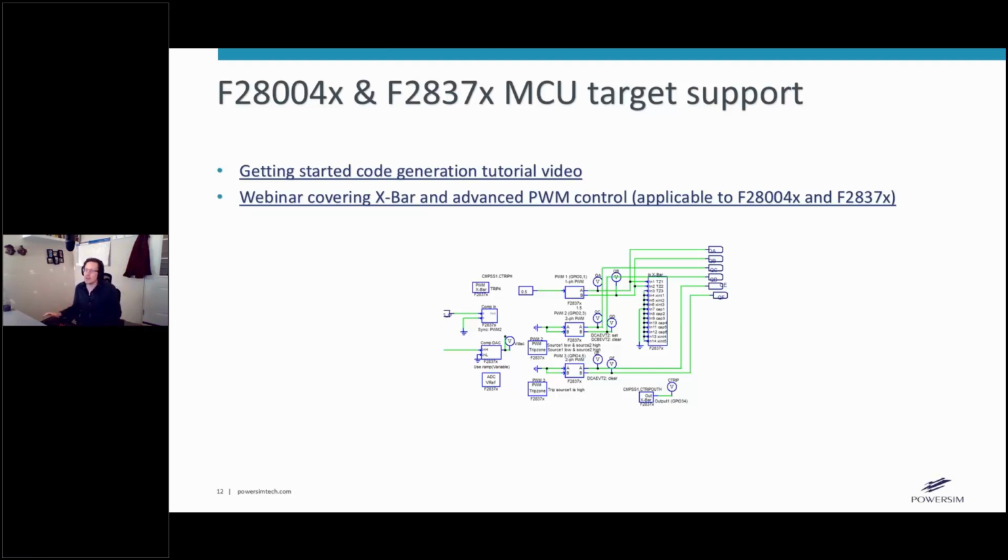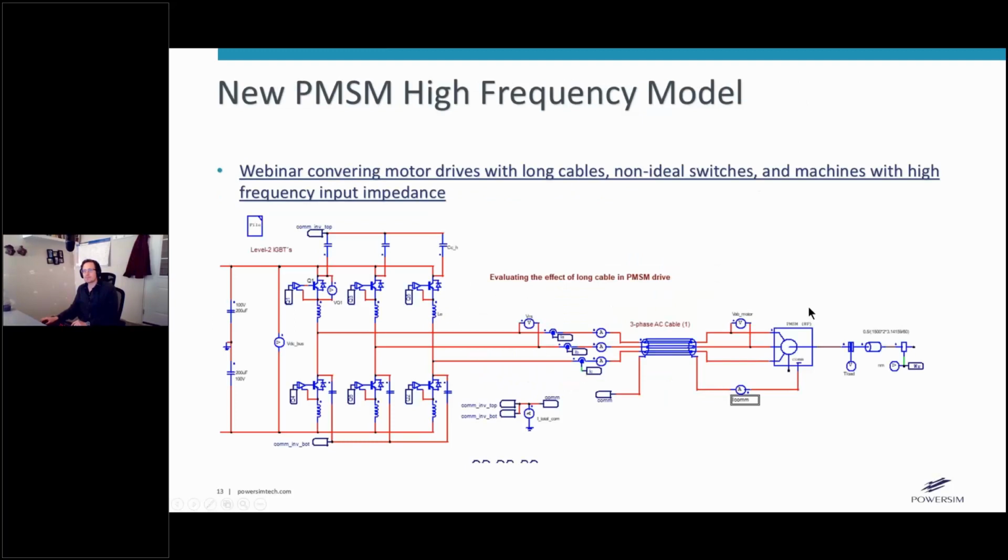It gets quite complex. If you're getting into this, a typical example would be a phase shift full bridge converter with peak current control, where you have an active secondary rectification. So you're triggering the phase shift on a peak current trip signal, and then you are triggering the active secondary switches based on the on times of the primary side. We'll look at that example quickly here, but definitely there's an hour-long webinar that covers this in detail. So we're not going to cover that in detail today. I'm just making sure we're running well on time. So definitely check that out too, okay?